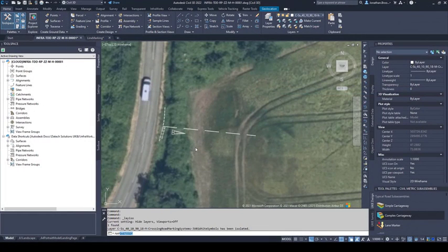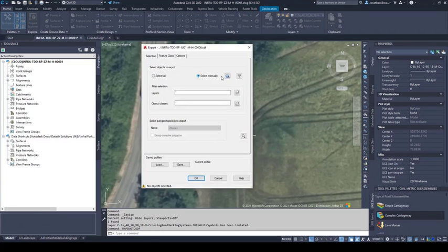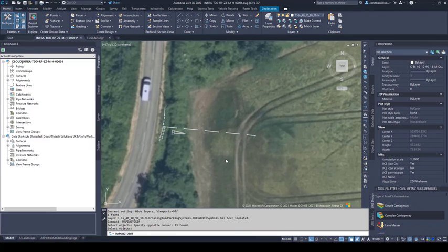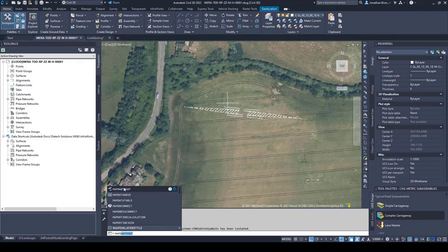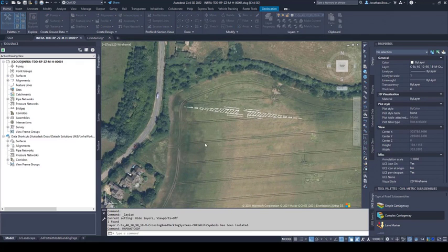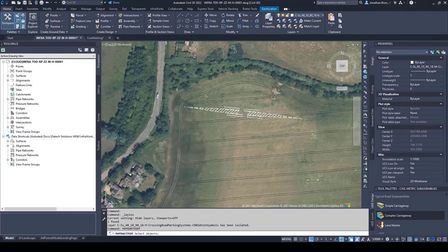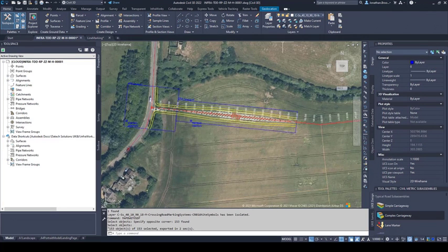Further to the application of shapefiles comes the addition of spatial data files or SDFs. For infrastructure type projects, or indeed the civil aspects of a building's projects, spatial data files allow us to include further context to our InfraWorks model. It means that we can include our line marking designs which have been accurately set out and dimensioned on the 2D plan as an overlay in our 3D terrain inside our InfraWorks model. Like shapefiles, we can export this information from Civil 3D, only this time using the map DWG to SDF command.